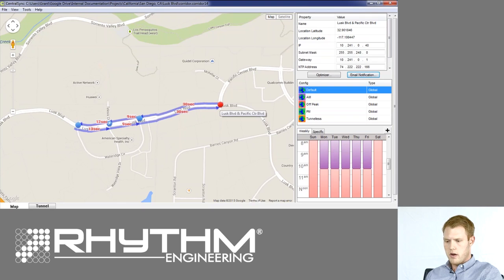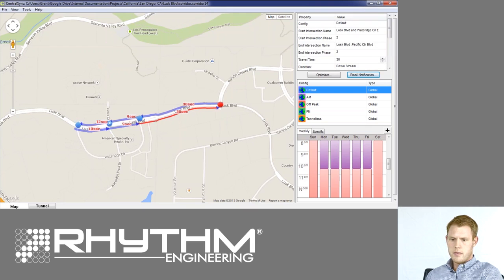Now let's look at clicking on a tunnel between two intersections. When you click on that, it will display more information in the property sheet, such as travel time, what phases are connected for the tunnel chain, and so forth. If you follow that down on the screen on the right side, you'll see a list of different configurations that have been created. In this case, there's been 4 different configurations created for different time periods of the day. AM, off-peak, PM, and tunnelless, which runs without coordination between intersections.